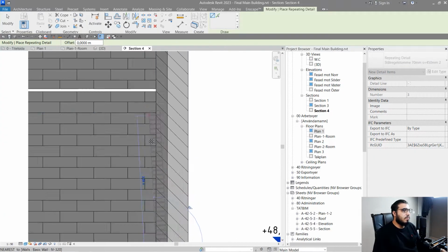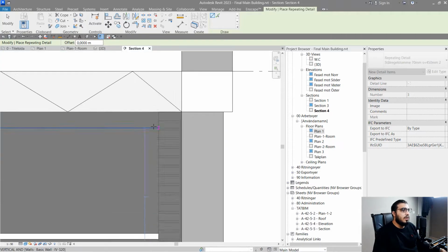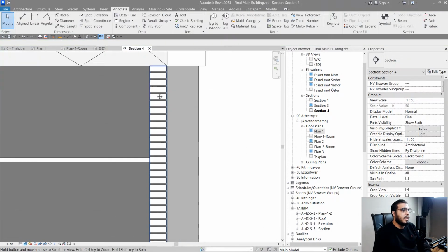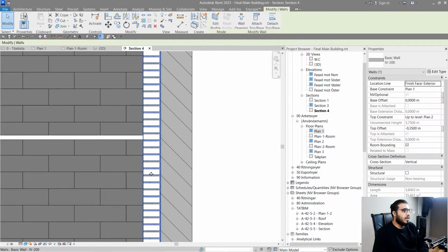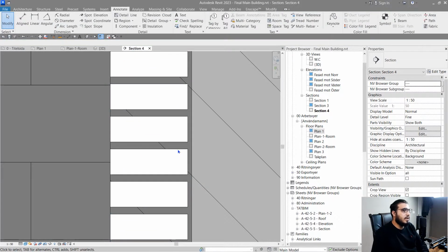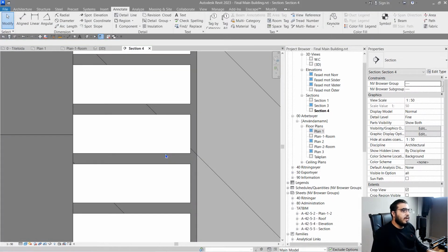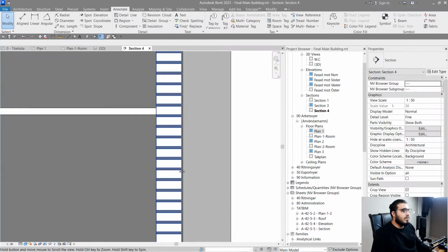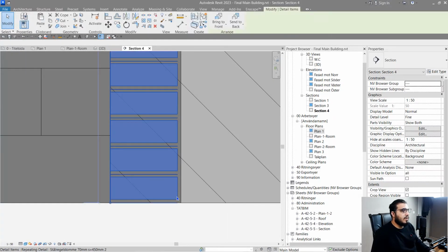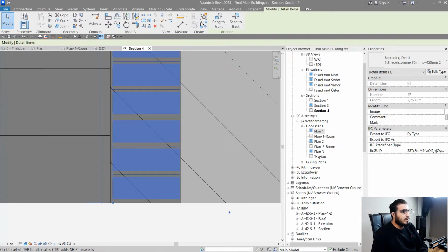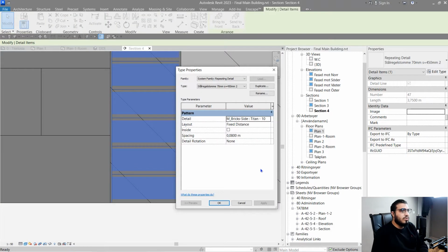Now we can place them much easier in here. Click once in here, and now you have your break item. You can change the layout of them really easily, and you can even go to the family and change the color of it, or you can change the color of it even in here. So that's an easy way to create your details, and you can change the dimension in here. For example, let's put it on 7 centimeter. Click on apply. Maybe 8 would be better.